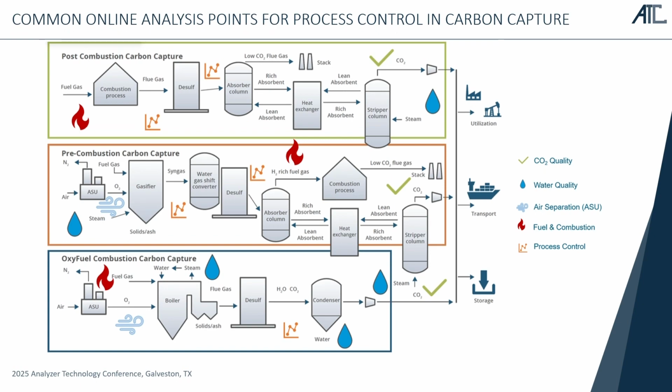Okay, and so what kind of things do people care about? Well, within the pipeline, if you have excess water, if you have H2S, if you have oxygen, of course these things are going to lead to corrosion, wear down the life of the pipeline. In the case of the project that we're talking about specifically today, their primary use for the CO2 is going to be for oil recovery. And so, in addition to your standard pipeline considerations, one of the critical factors they're concerned about is the potential for breakthrough coming out of the capture process.